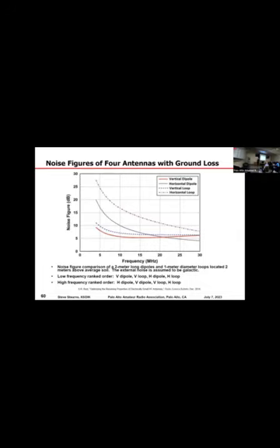So noise figure for an antenna is just the noise figure based on the noise at the terminals of the antenna. It is usually done in radio astronomy terms in degrees Kelvin, but microwave engineers prefer to use decibels and noise figure in dB. Beyond that, I'll just refer you to books on radio astronomy antennas.